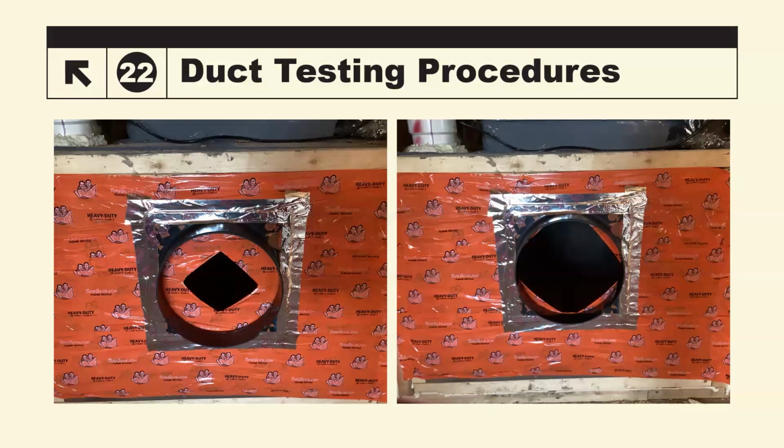It would be a write-up in the report for QA, because in my opinion this isn't done right. If you know anything about duct testing, these systems have different size openings called rings that you put on the system to accommodate leakier ducts or not-as-leaky ducts.